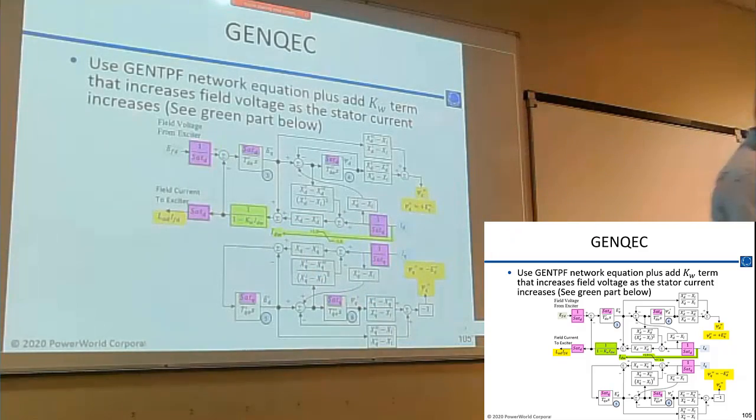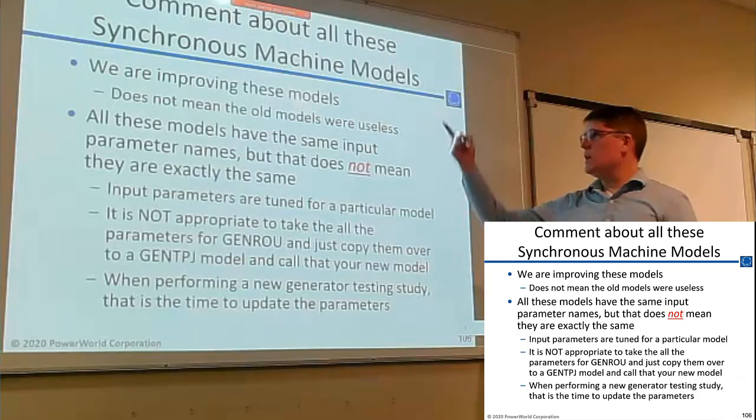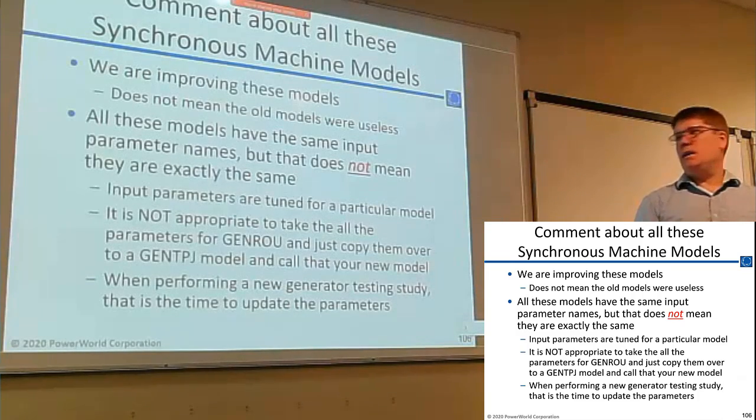All right, one last comment about the synchronous machines. If you want to switch from a model you have now over to, say, the Gen QEC model, it is not appropriate to just take the parameters you have and copy them over.